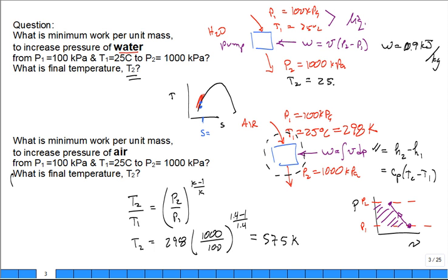You know, we're getting approximate numbers. I'm not trying to get 3 significant digits on that number. It's close enough to 1. I can call that number 1. I know it's 0.9, but I'm not struggling. Is it 0.921 or anything like that? Same here. I'm trying to get in the ballpark. So what's the specific heat of air? About 1. Okay, 1.005. It's about 1 kilojoule per kilogram Kelvin.